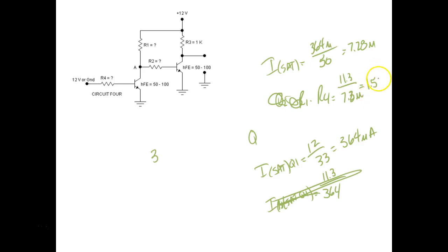That's megohms. And then what should we do? Go down at least one, right? So what's the next standard value below 1.5 meg? Okay, so 1.3 meg times 1.05. What does that give us?